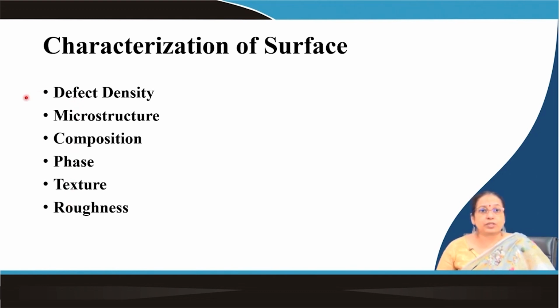So, microstructure consists of the size of the individual constituents and their distribution, the phases present, and the direction in which they are growing. And finally, composition is also an integral part, because the microstructure remaining the same, the composition can also vary.